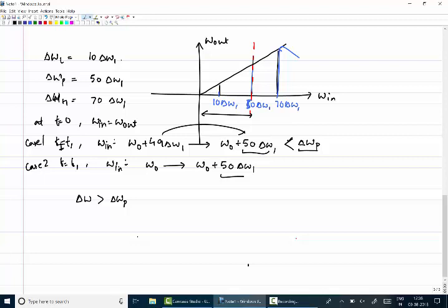And if you want to come back by going back two steps, it is actually a frequency which is more than the pull-in range, so the PLL cannot pull in at all. You have to come back to a point which is within the pull-in range of the PLL.